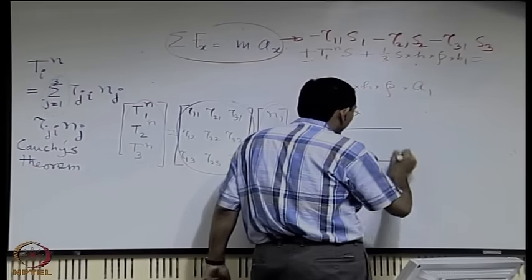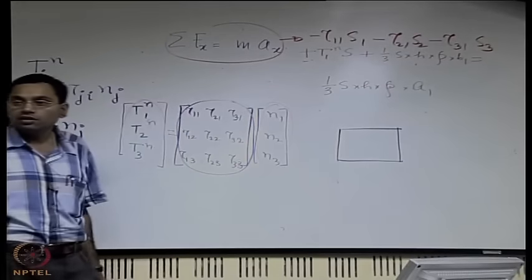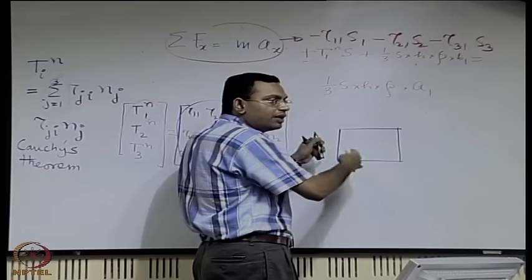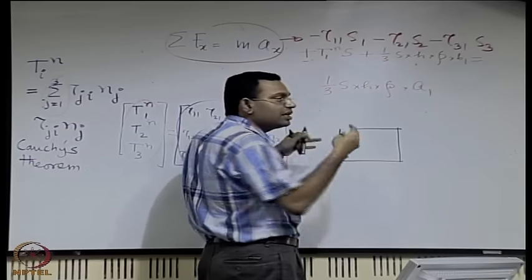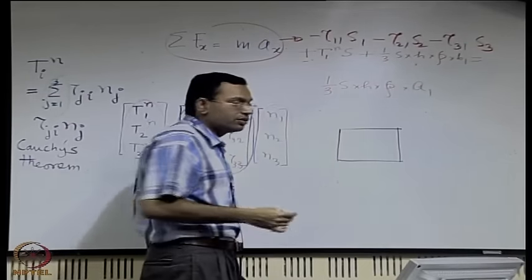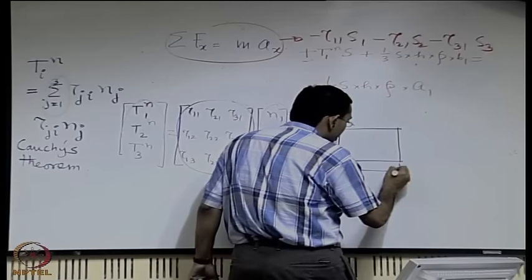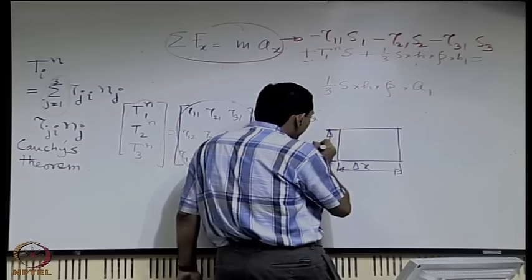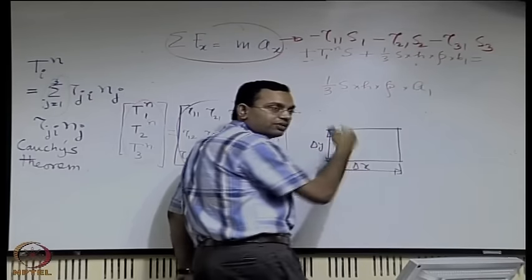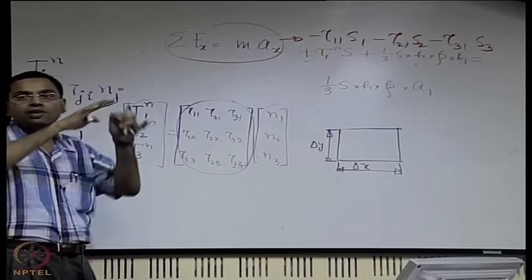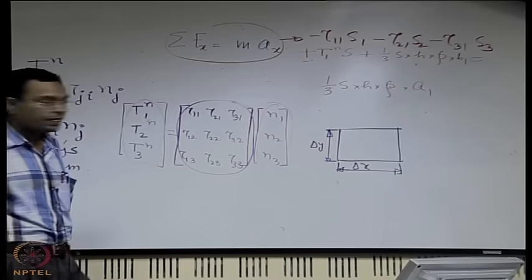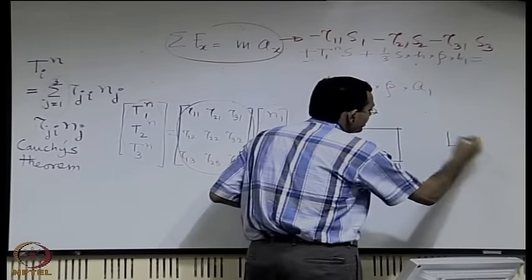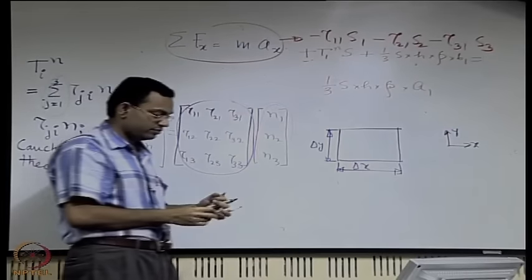We will consider now a 2-dimensional element. A 2-dimensional element is something where everything is occurring in a plane, just for simplicity. So we are assuming that the third direction is like unity. Say this is delta x, this is delta y. Just imagine that it has faces perpendicular to the figure, all with width 1. So let us write the components of the stress tensor on these surfaces.